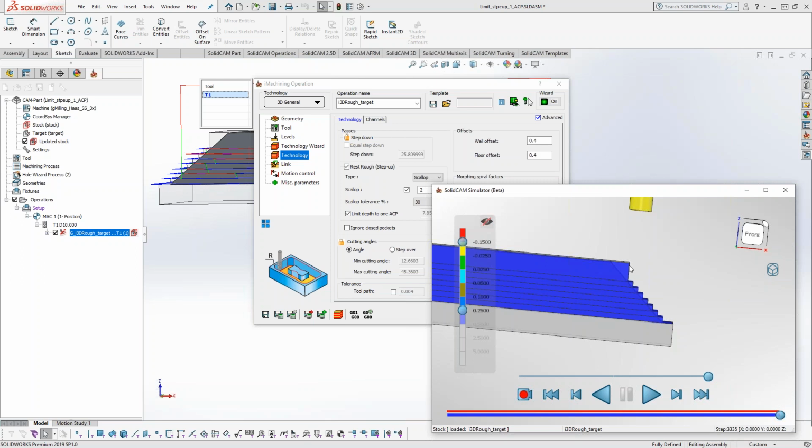A lot of customers nowadays are starting to use special tools for iMachining, because the way iMachining can manage the cutting force and the load, you can get a better, more expensive tool that has special grinds that perform better with how iMachining is meant to be: a deep depth of cut, very controlled engagement, and very controlled chip thickness.